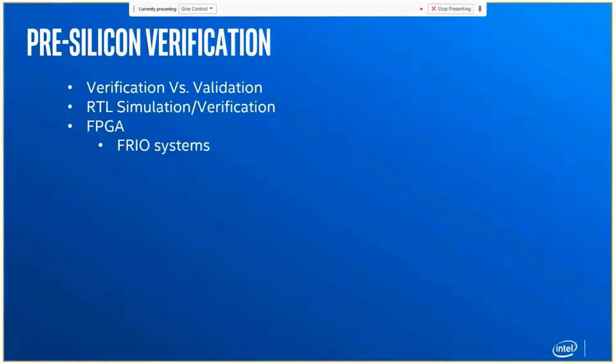So functionally, it's a kind of high fidelity simulation of what the chip will do, but at a very, very, very slow rate and in parts, right? So that's the FPGA simulation. Beyond that, there are also software simulators. They may not be exactly mapped to the silicon verification itself. It's sometimes the other way about.